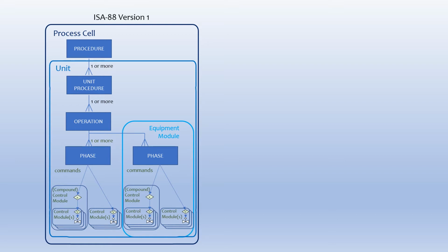Another type, coordination control, is not shown here to avoid clutter, but that's the glue that connects the control to the physical groupings. The procedural control is the bit that causes the transformation of material into product. It always acts on the batch. The bottom level phases requests action from the basic control to affect these transformations.